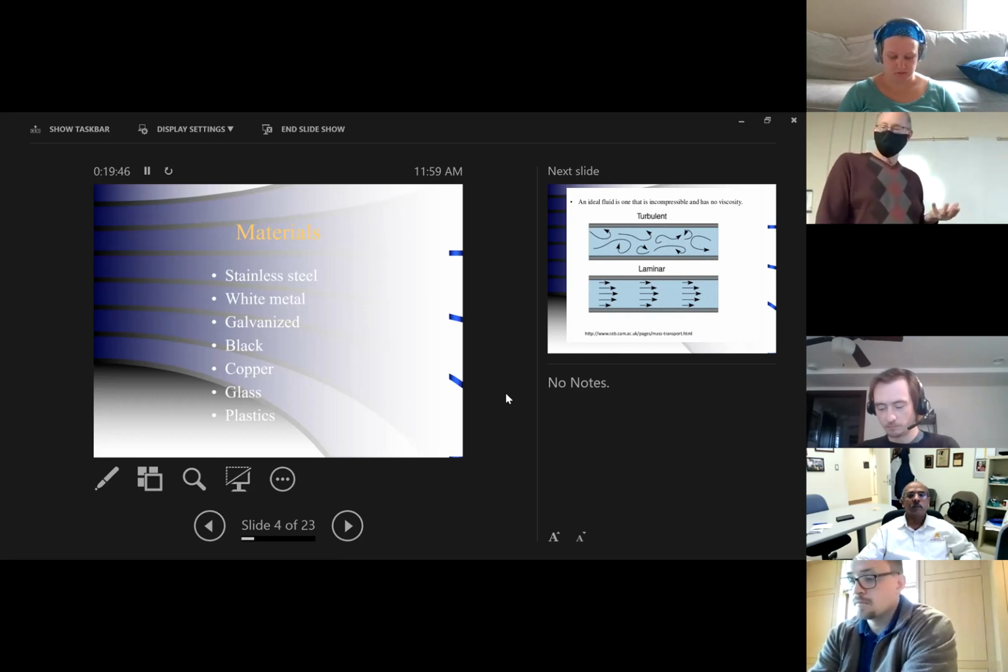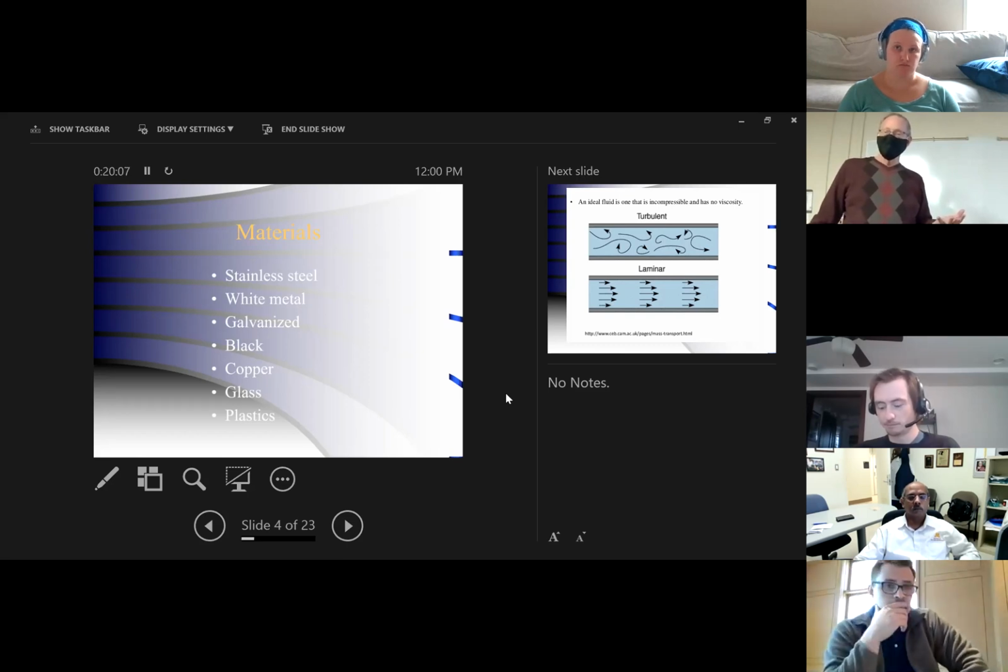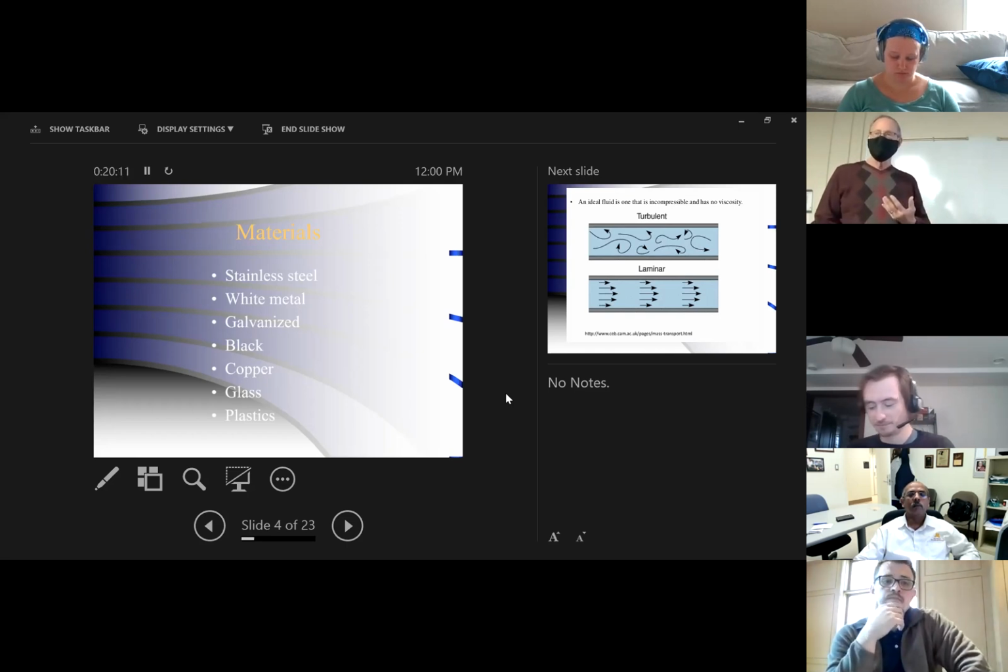Glass piping, and there may be some of you who already wonder, why would we want glass? Because glass will break and glass can cause problems. And admittedly, not a lot of glass is used, but where is a good place to use glass? In your laboratories, for your drain pipes. Because if you're doing things like ether extractions, although you don't want to be pouring that down the sewer, that better be taken care of other ways.